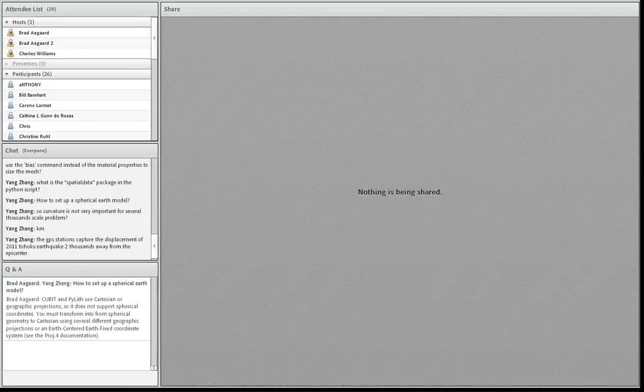If you're selecting commands, because the apropos commands begin with a comment character, sometimes it's easy to skip over them and miss that units equals SI at the beginning. Those journal files for the 3D meshing didn't have any apropos commands in them, so that's a little odd.